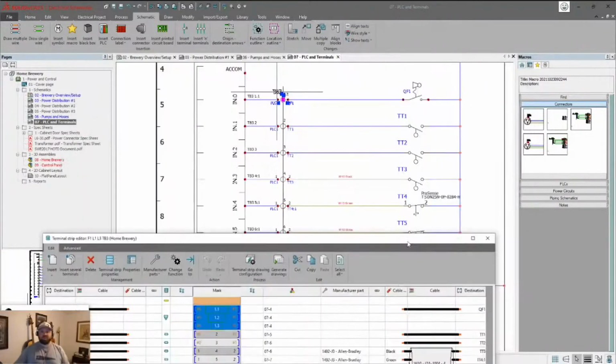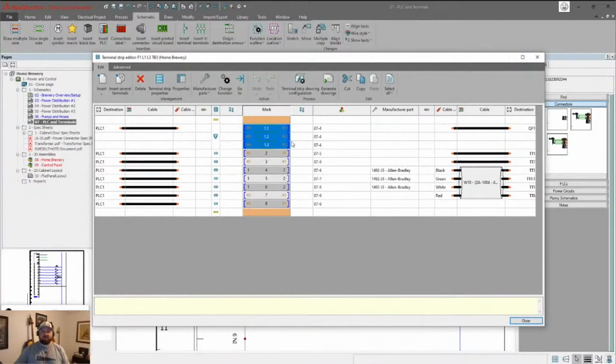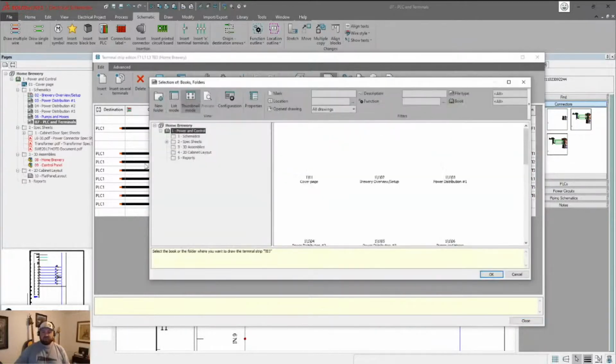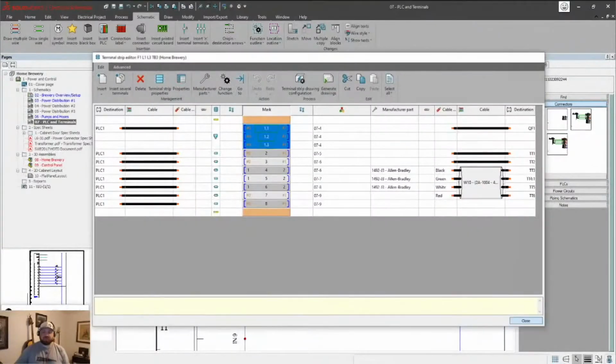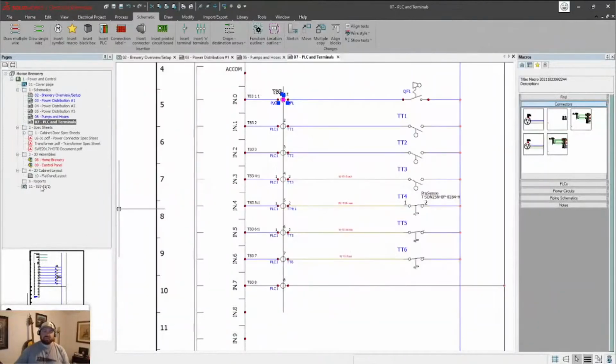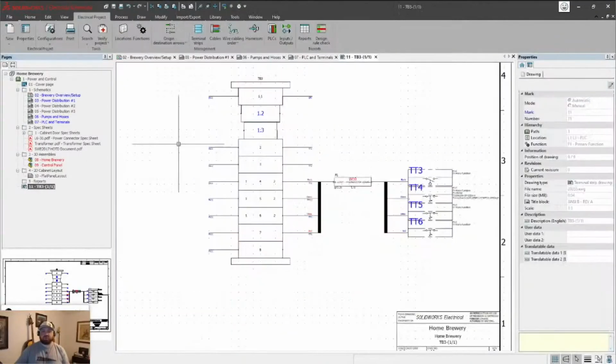It's not really displaying on my schematic like that, right? How do I know that that's a 3 level? Well, there's this option here to generate drawings. I can let the software use a configuration. SOLIDWORKS Electrical uses some configurations to allow us to automatically create things. So it's essentially a report of that terminal block. So instead of handing somebody a schematic and saying, here, figure it out, you can also generate this drawing and say, all right, this is terminal block 3.